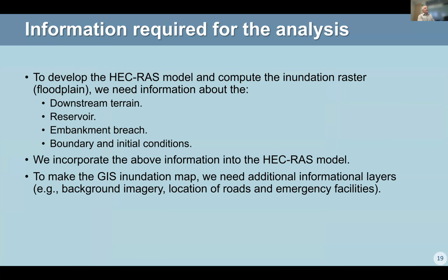So what kind of information do we need to develop these models? Well, we need the terrain downstream of the dam. We need to know something about the reservoir because that's the water that's being supplied. It's going through the breach and out onto the floodplain. We need to know something about the embankment, like how big is the breach going to be? How long does it take to open? And then we need to know something about the boundary conditions, and I'll talk about those later.